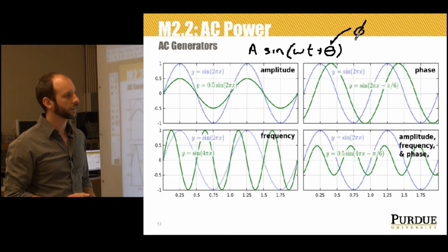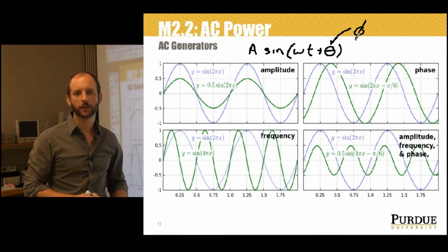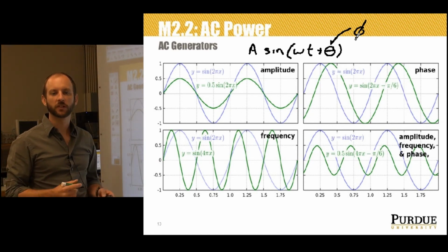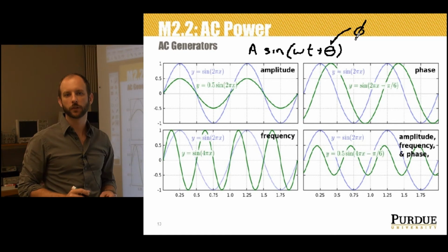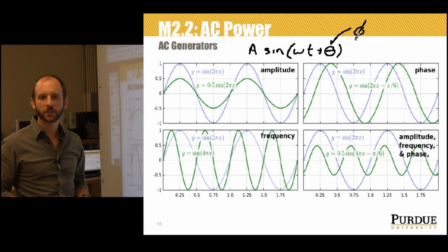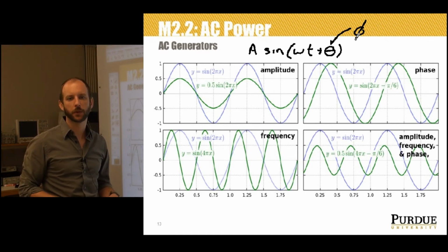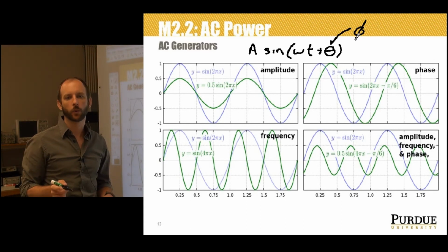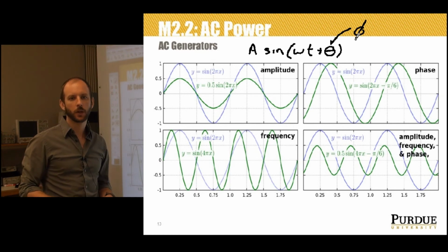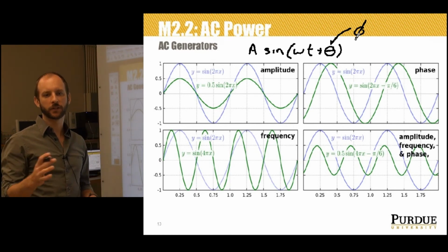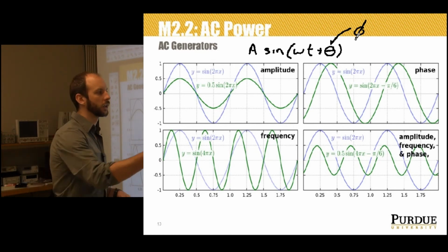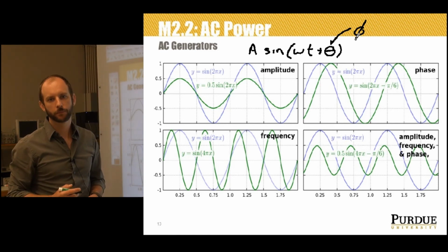Phase, in this case, I'm going to use the lowercase symbol phi, represents a delay from the original starting point of a sine or cosine wave, or a separation between 2 sine or cosine waves, measured in degrees or radians. This can also be thought of as the angle by which the sinusoid is displaced ahead of or behind where it would have been had it started at time 0. Graphically, it manifests as a shift of the entire curve, either left or right.